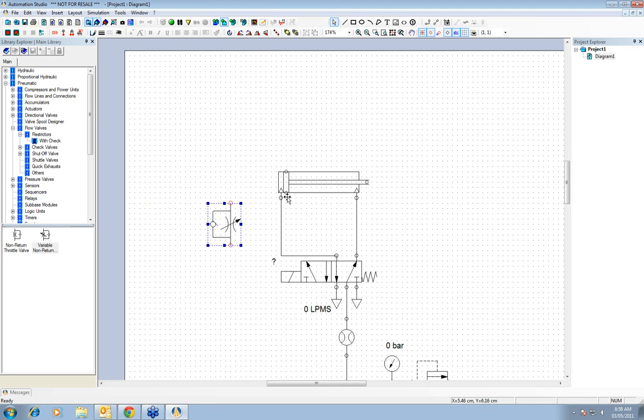Now, one of my tips is that if you are going to use one of these, make sure that you flip all of your components before you actually insert your component on the line. Because if you do not put the component apart and then flip it, if you do it on the line, you're just going to create a twist of all the lines right here.